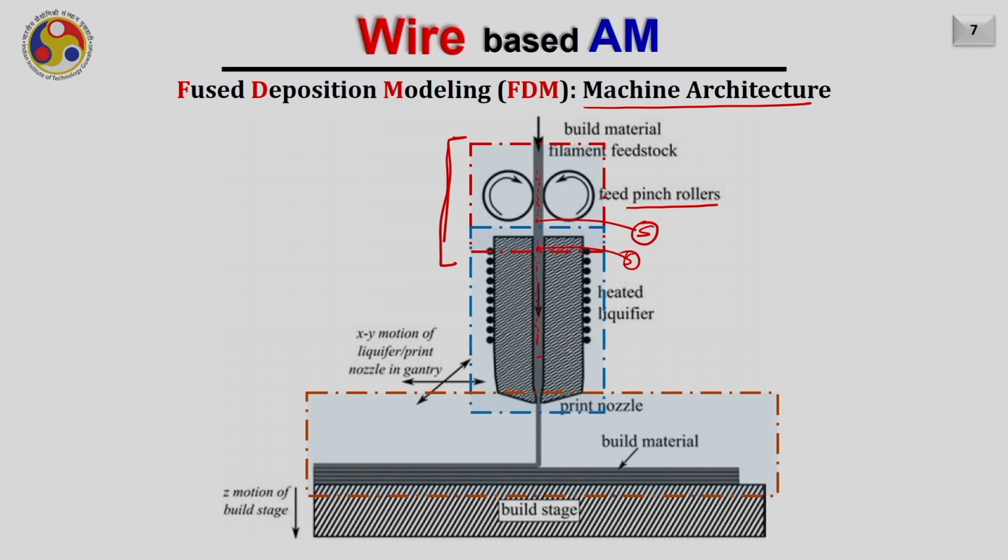So assume that it is melted here. Now this solid wire acts as a piston and pushes this molten region of the wire through a very tiny orifice. So this is the orifice. Of course, to push the wire through a tiny orifice as compared to the entering area, you need to add some additional force from the top.